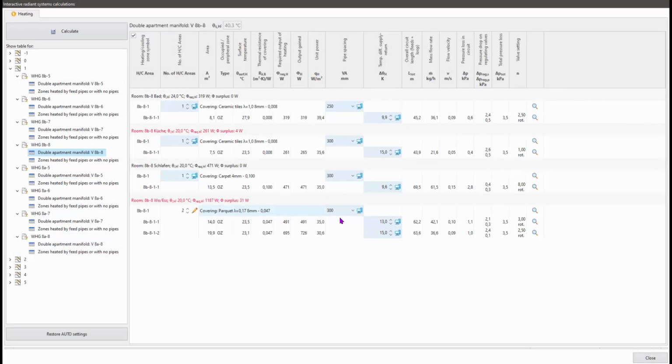Changing the cooling value of the medium in the deltaT field results in an immediate recalculation of flow parameters, obtained output and settings on the manifold. Thanks to this, without the need to perform full calculations, you can correct parameters in individual loops in a flash.